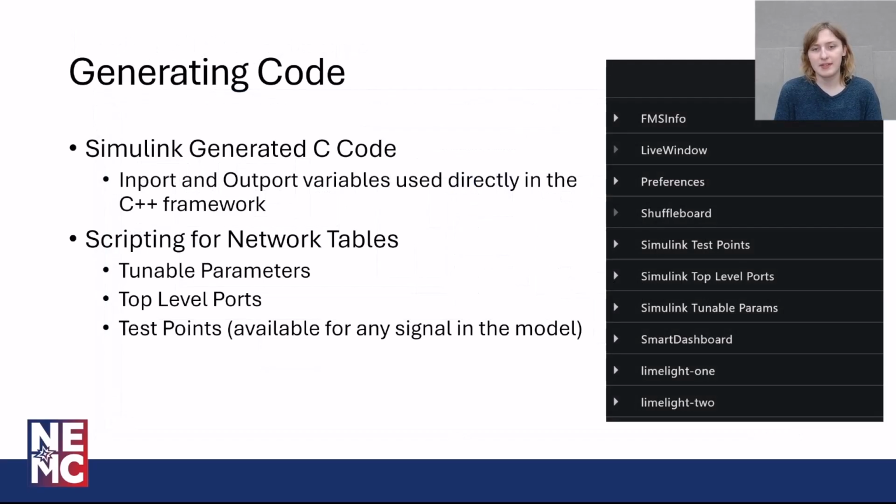So that's kind of how the Simulink works at a high level, but how do we integrate this with the C++ code and WPILib? It's through the build script. The inbuilt Simulink coder generates the C code with some settings changed in the configuration, with an additional build script.